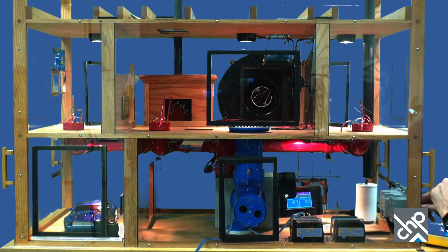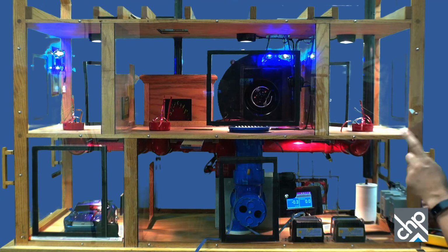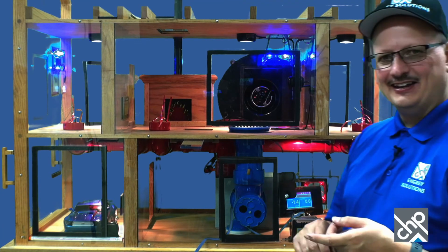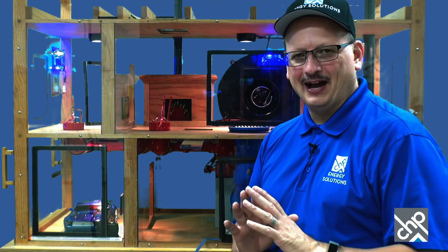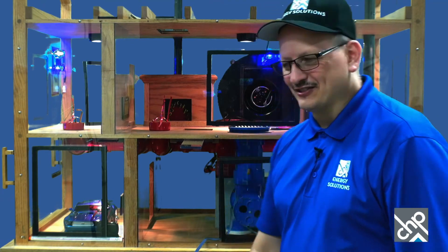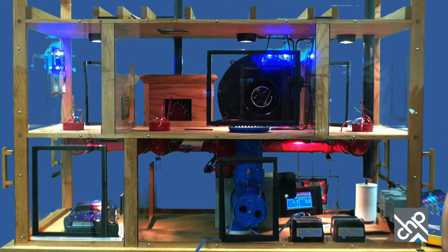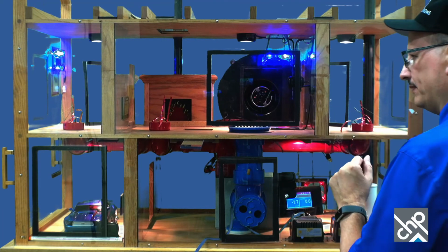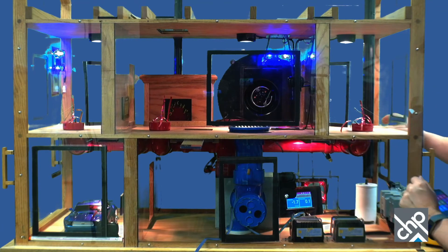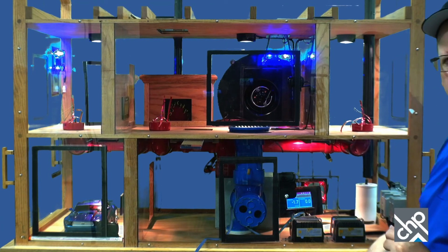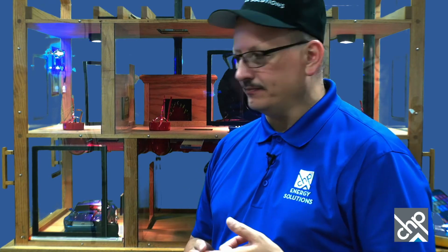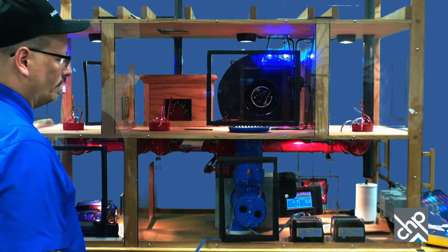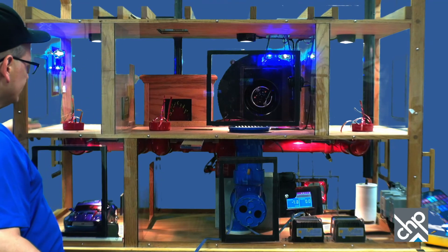So we want to turn on what first? Small fans, right? So that's going to be my kitchen fan, bathroom fan, dryer. Again, this is a lot easier on a small house. You get everything in one spot, but the concepts are the same. You just get a little more exercise. So got on the exhaust fans. We've got all the interior doors at this point open. I'm going to close those, and then you would do what with the doors? You would check the ones that have fans behind them with smoke, or you can open them, close them, and see the pressure change. I'm closing those doors.